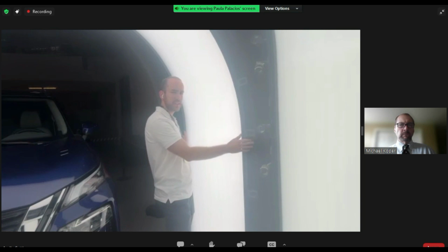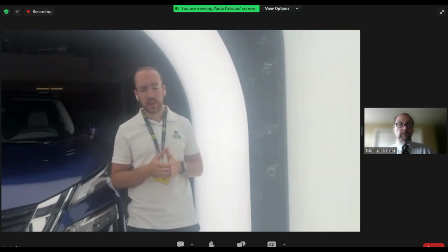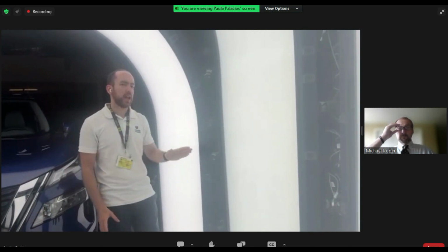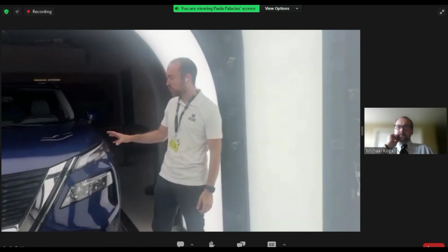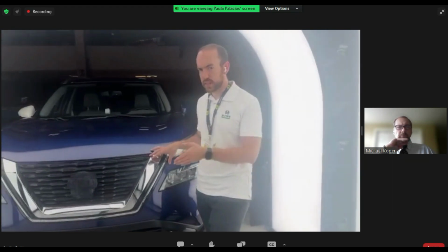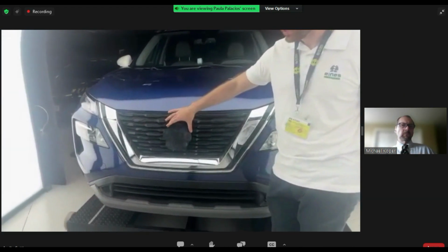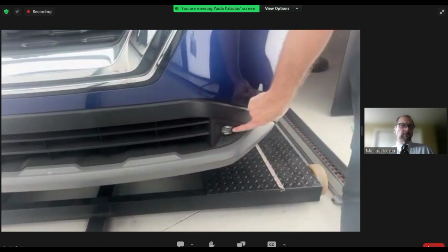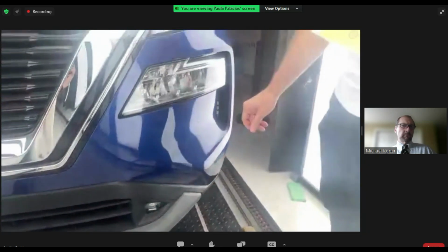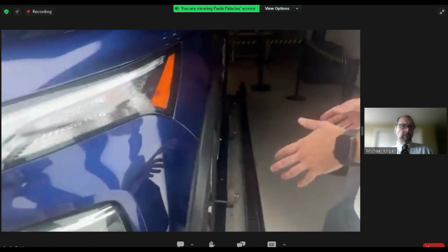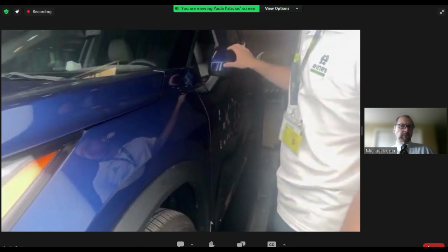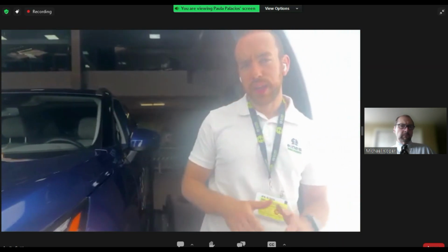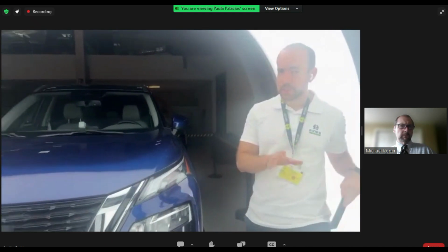And by the end, this last arc is responsible for the spec check. This spec check is not only by this light, it's helped also by the other lights. It's using the same cameras as metrology, and we can add extra cameras if required. It is responsible for checking if the car is completely and correctly assembled. That means the logo is correctly placed. Should this be chrome or plastic? Do we have this light? Do we have sensors, parking sensors? But not only about presence, we can also check materials, plastic or not, or colors. Is this mirror in the correct color? This is something that is solved by the spec check, by the last part of the tunnel. The last but not less important.